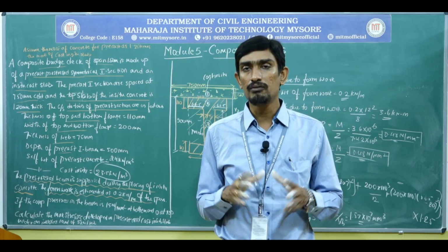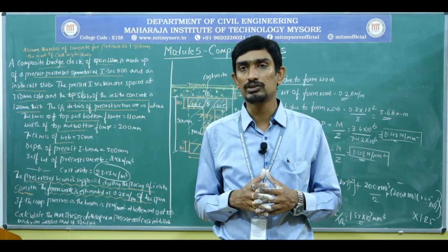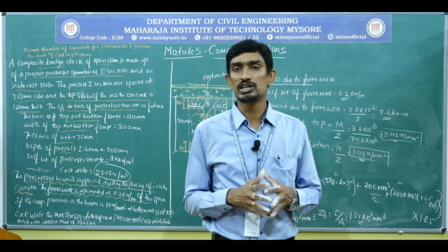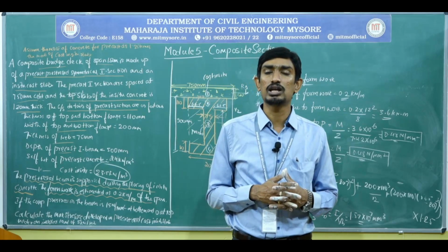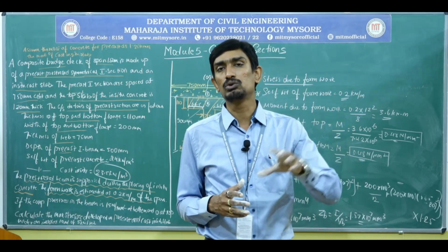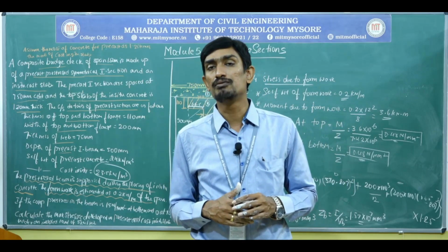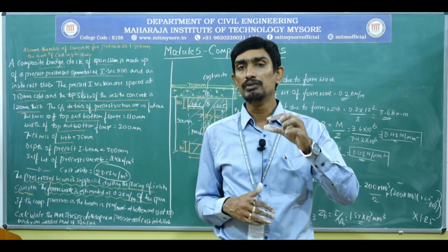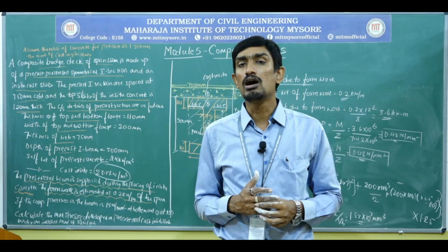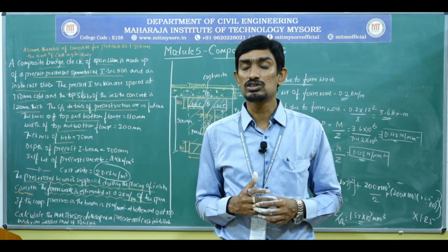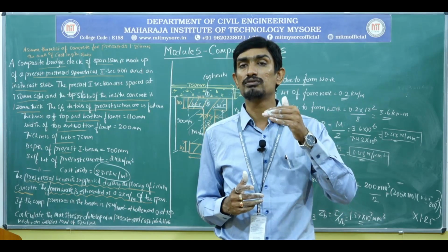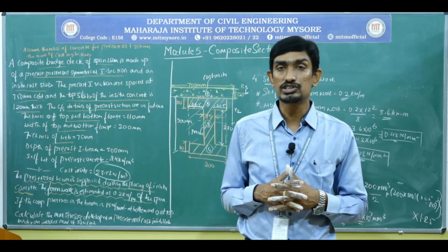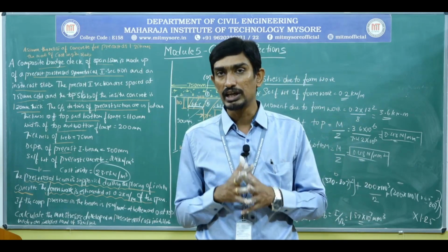What changes from the last problem is, when you come across a propped case, we need to calculate the stresses due to self-weight of the cast in situ slab with respect to the sectional properties of the composite section. That means Z top and Z bottom we need to consider for the composite section for the stresses due to self-weight of the cast in situ slab when calculating stresses for the propped construction case. That is one change.